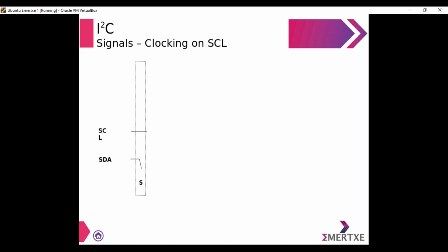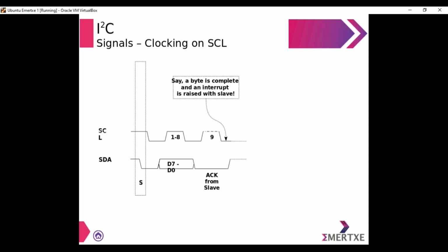You can see, the clock pulse gets generated, data transmission has happened. So communication is happening. In the data line, data is transmitted, acknowledgement is being exchanged, everything is happening. Now, after some point of time, microcontroller 2 gets some very important task, but it is acting as a slave. So what it does is, it pulls the line low. It keeps the clock stretched for a certain duration.